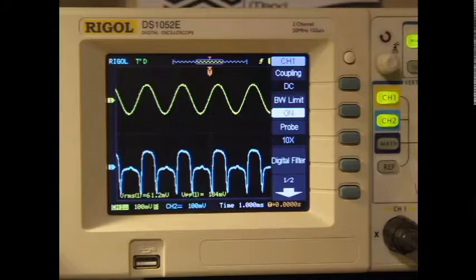Why is that? Well, that's actually a little bit by design. The diodes that do the rectifying in this thing are germanium. I use germanium diodes because they have a fairly low forward voltage, which makes them well suited to this application.